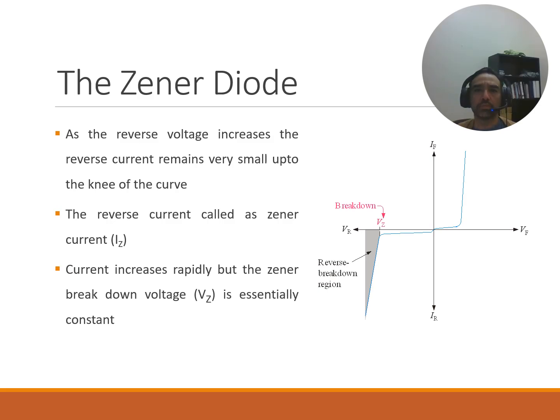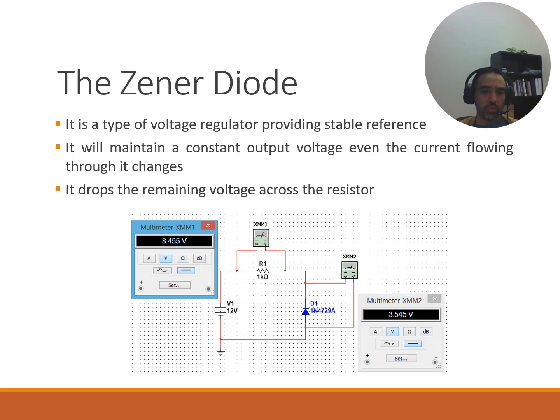Alrighty. Okay, so in this figure, we see a Zener diode, and notice that it is in the reverse bias configuration, where you have the cathode up and the anode in the bottom. The anode is connected to the lower reference, the negative reference of the battery, and the cathode to the positive reference of the battery. So this is the way you would actually configure it in a circuit. There's a resistor there, and then you have your 12 volt source.